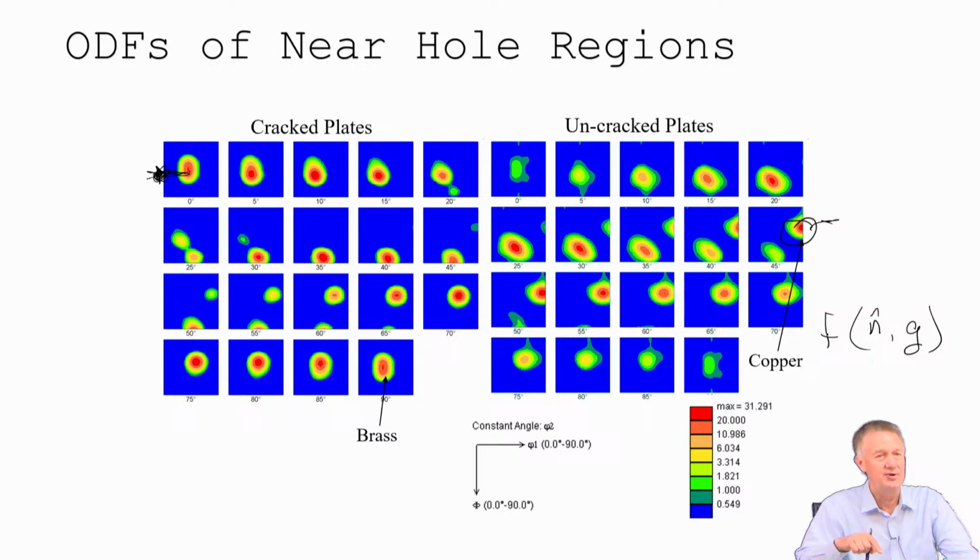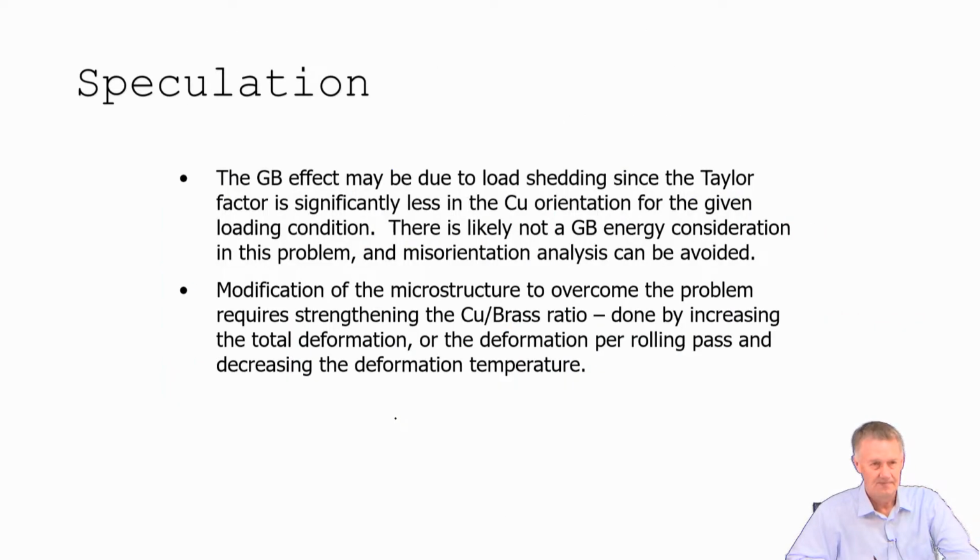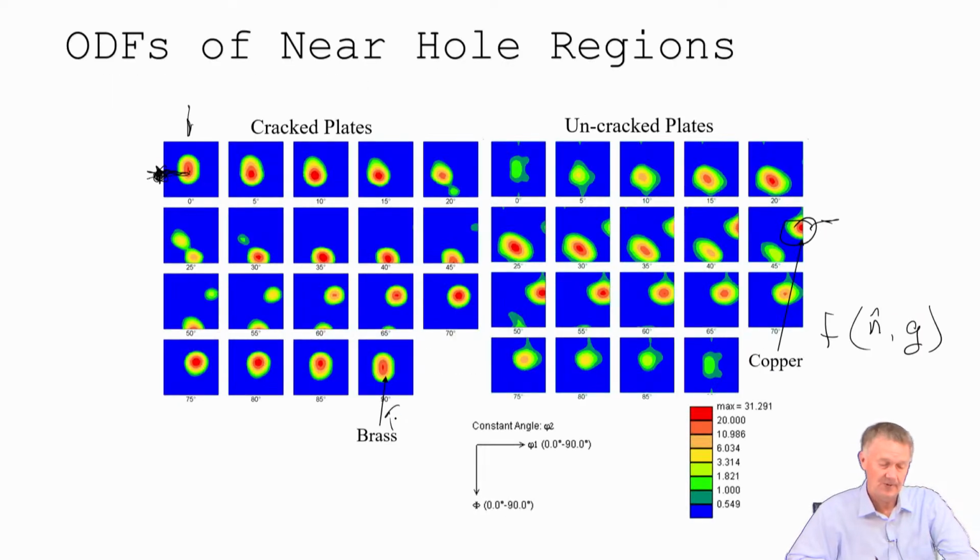And then when you consider orthotropic symmetry, there's an additional factor of 4 times that, right? So we've rolled the sheet, we've rolled the plate, so we say there's a factor of 4. So because of orthotropic symmetry, this is the same as this, is the same as 180, 270, 360. They're all exactly this, showing the same components. That's correct. These both are fiber texture. Yeah, so FCC rolling, you go from Gauss to brass, which is a really nice, you can see that very clearly in your fiber texture.